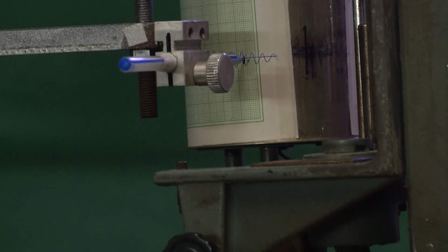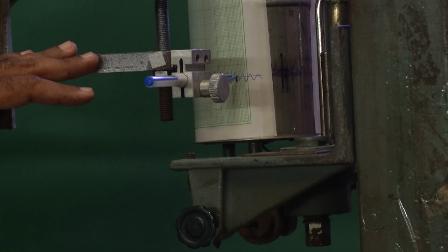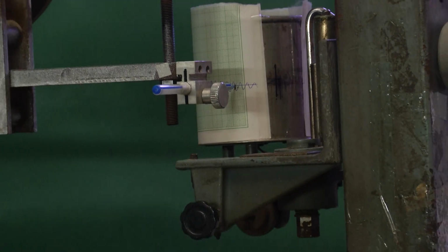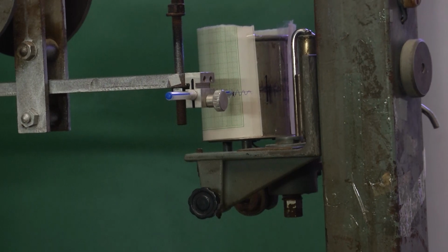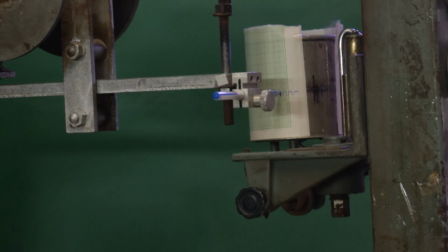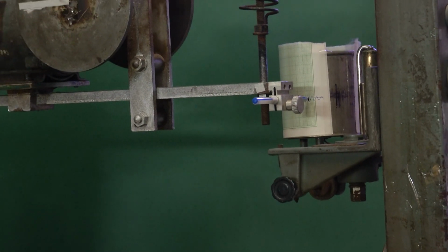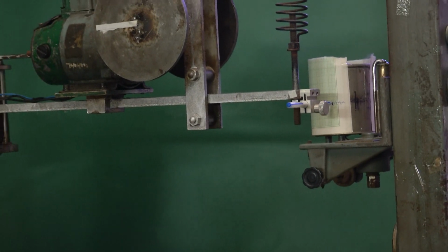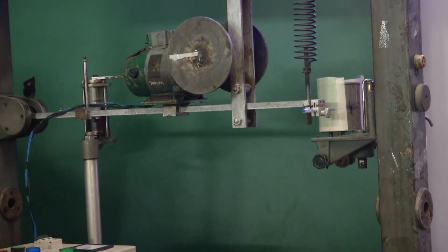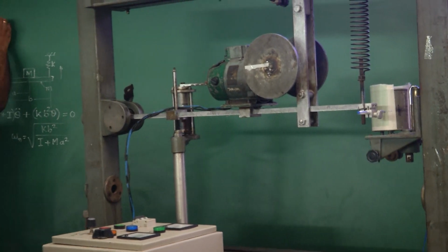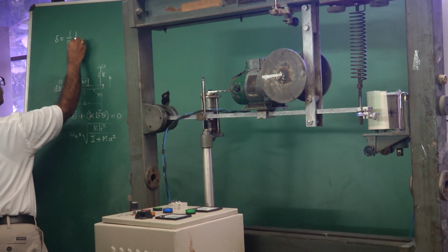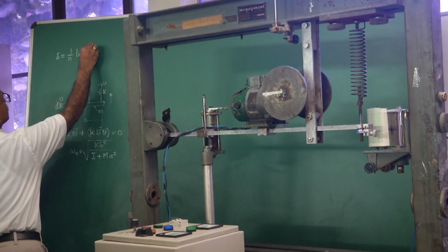that system. Okay. So, now what can be done is, because you have a graph of vibration amplitude as a function of time, you can pick up any number of cycles. Even the continuous 2 cycles can be used for finding out the logarithmic decrement. Now, the logarithmic decrement we all know is basically related to the natural log of the successive cycles.